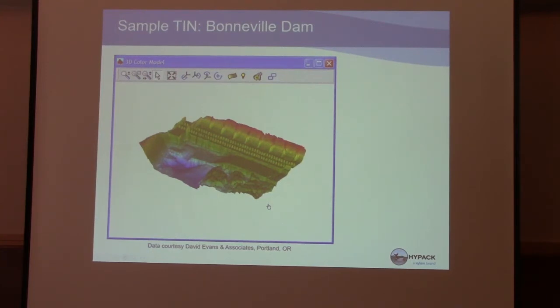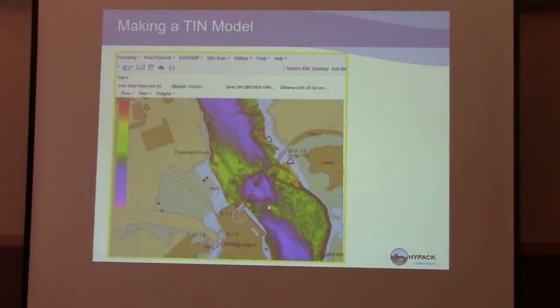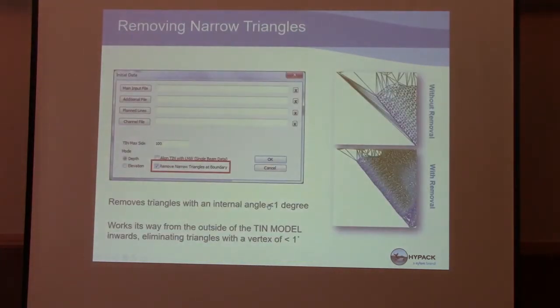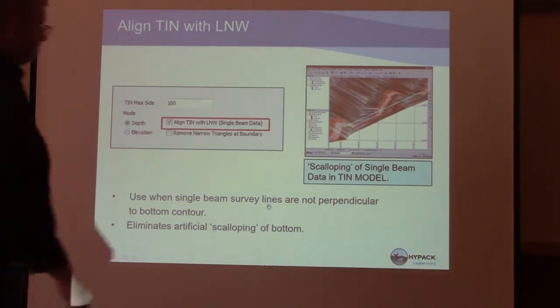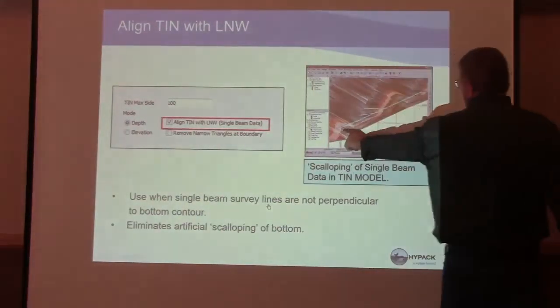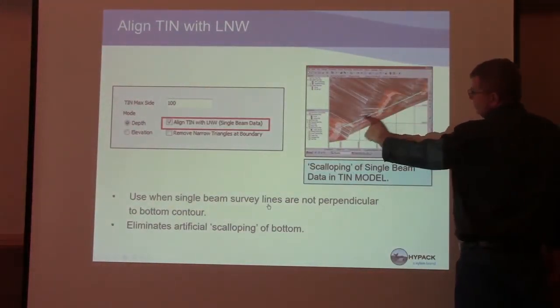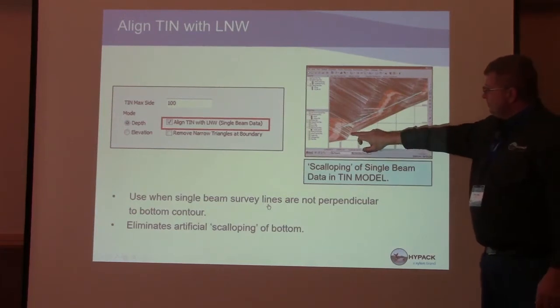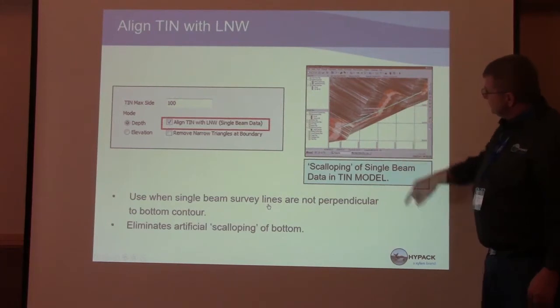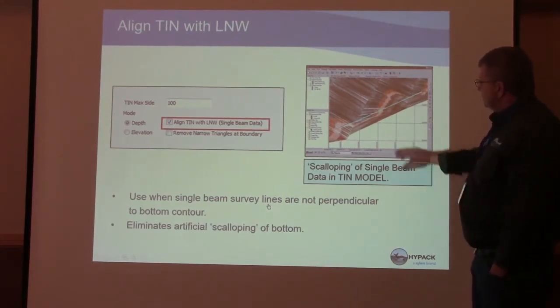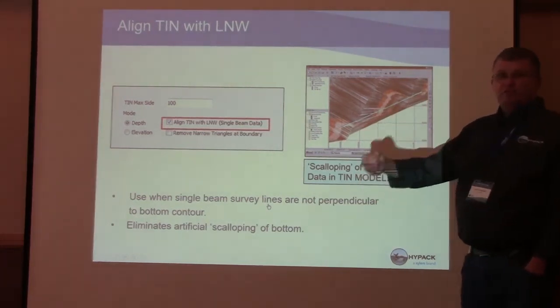Yes, sir. Previous slide, any question on align TIN and single beam? Yes. Could you just describe that? So it projects your TIN connection points to the line. So in here you can see the planned line. Here's where the plan line is. Right. It moves your sounding points to your plan line.